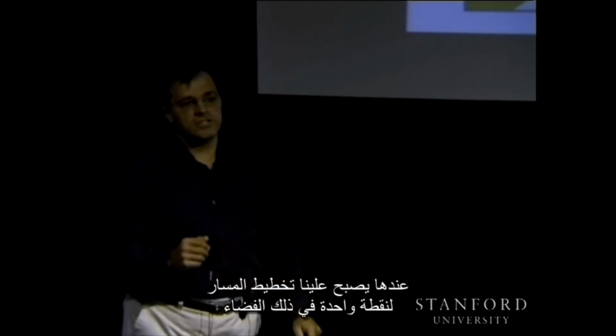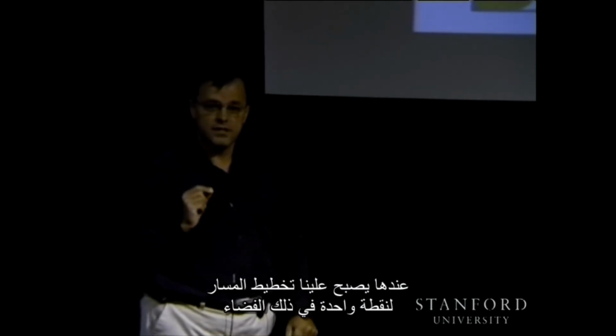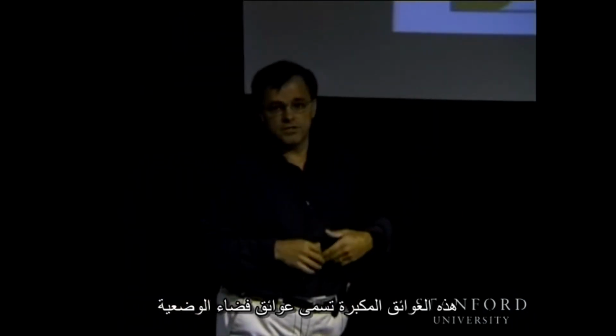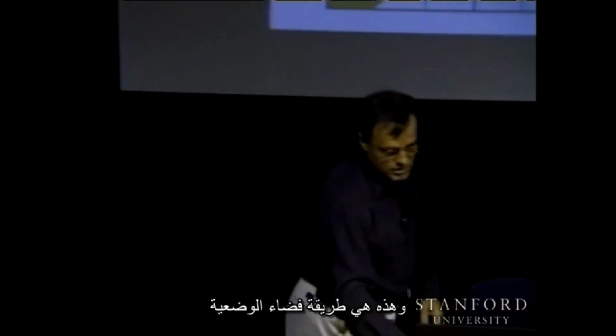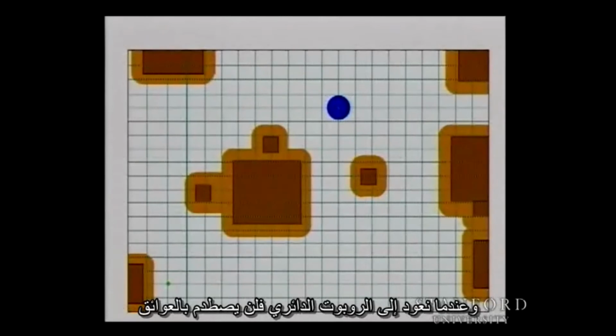And so then we just have to plan a path for one point in that space, which can be done in many different ways geometrically. These grown obstacles are called C-space, configuration space obstacles, and this is a C-space planning approach. We can put a grid around it and plan the path of the point around this grid so that it doesn't collide with the grown obstacles. Then when we get back to the circular robot, it's not going to collide with the obstacles itself.